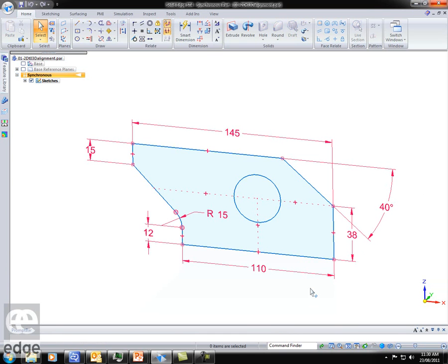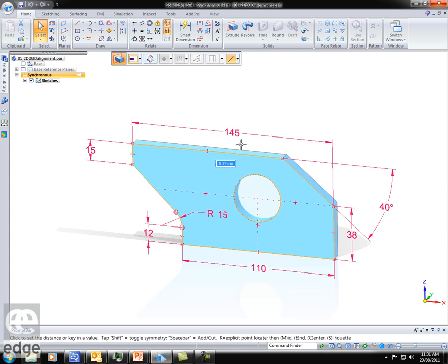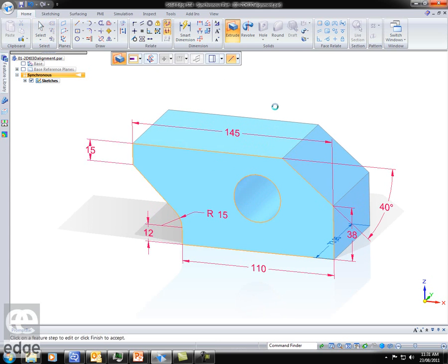Here's a common situation that we have with Sketch. We have the ability to apply horizontal vertical relationships between key points on other pieces of geometry. In this case, the circle there has a horizontal vertical relationship to the center of the angled line on the left, to the end point on the 38mm line on the right, and to the center of the 110mm line on the bottom. Now, in the past, when we extruded that, those were just simply lost. Let's see what happens now.